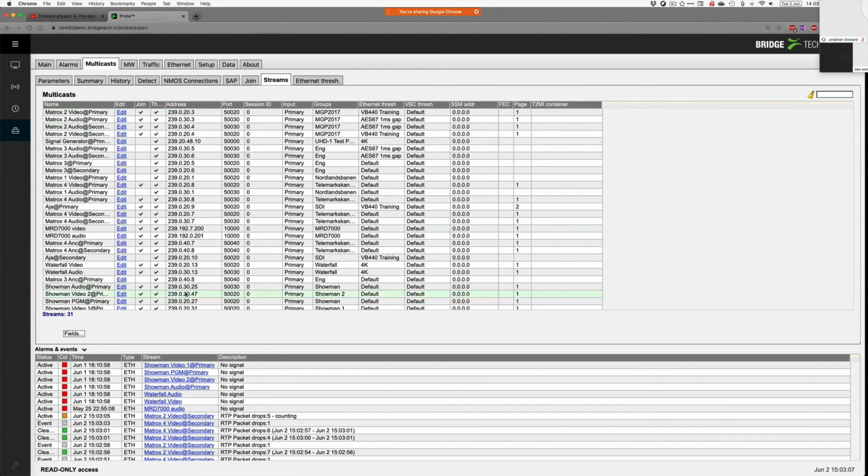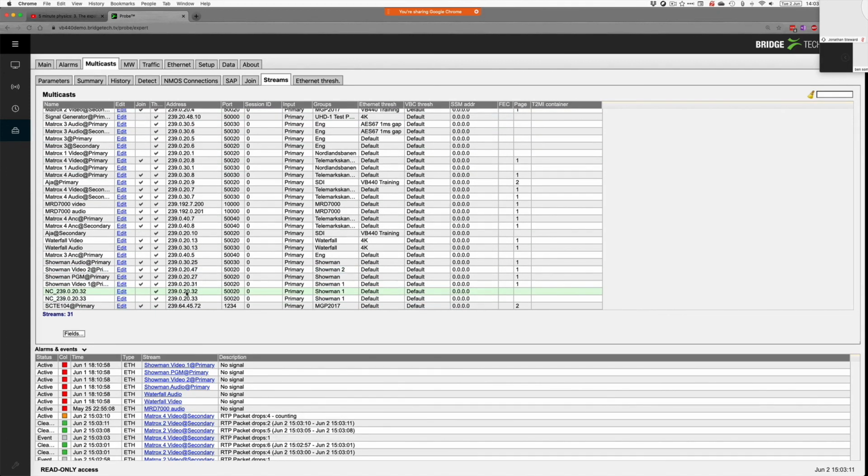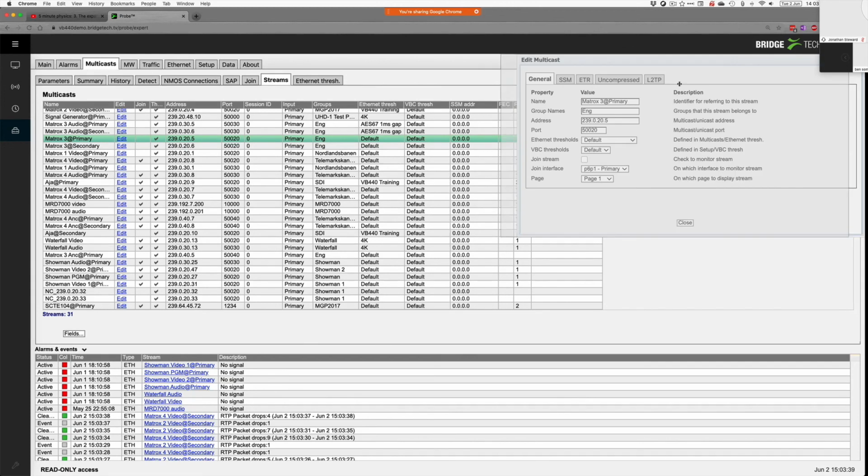And it's exactly the same as a standard IP probe. You join the streams by adding the multicast. There's one difference, and it's a significant difference because we have flows in ST2110. We have these flows. So a stream of one particular TV channel is made up of audio, video, and ancillary. So we have to group these together to make one stream. And this is how it's done. It's done quite simply, actually.